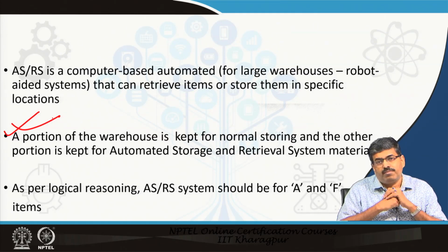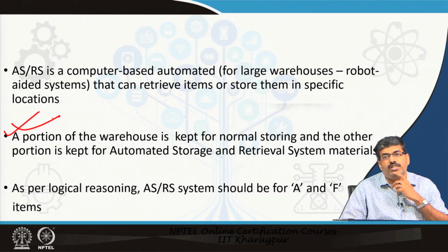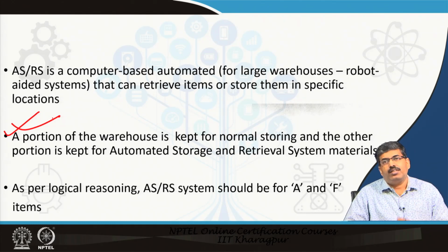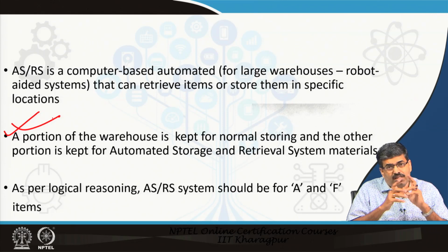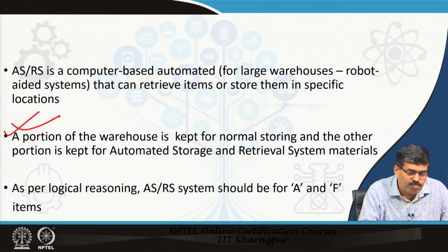Number 1, the warehouse is very busy, but what is the cost of the items that you are storing? 10 rupees per unit cost. Not feasible. So, ASRS system is feasible when it is busy and when the material stored is very, very costly. If a material is not costly, then you do not spend that much money on capital investments. And third, very busy, costly material. That is what we are saying in point number 3.